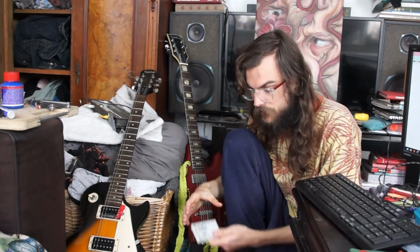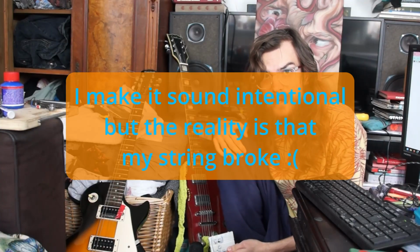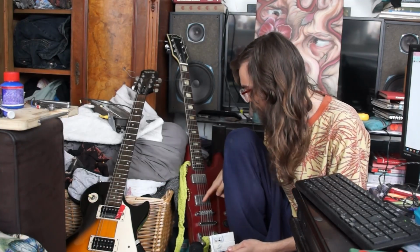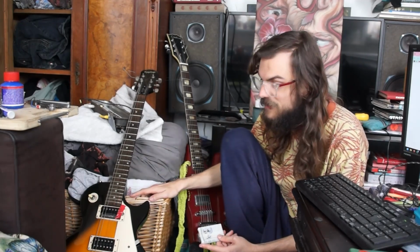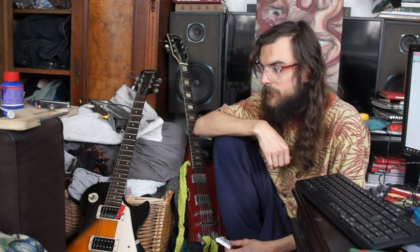I was testing the prototype that we just built on these two different guitars, and then I realized that they sounded very different. And that's because a huge factor with this design is that the voltage of the guitar itself creates a huge swing in how much this circuit actually distorts the sound. Because of this, I think the best idea is to make a second amplification stage so that we can more accurately tune the input voltage of our signal.